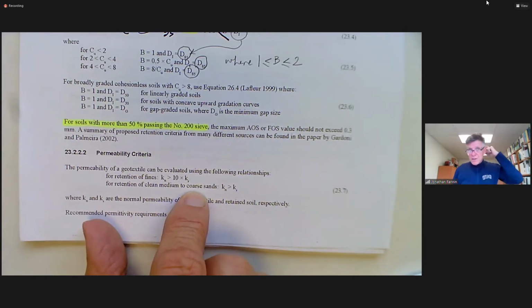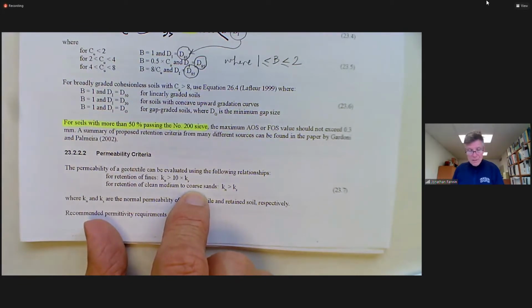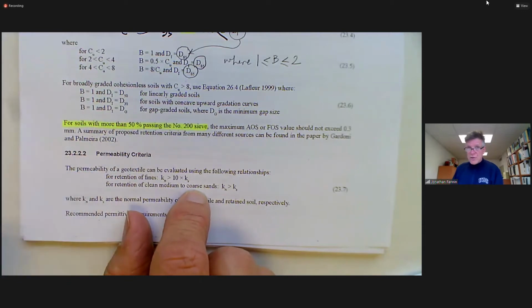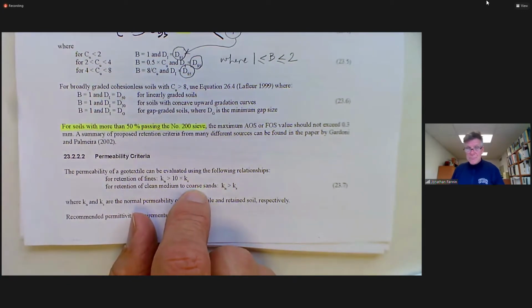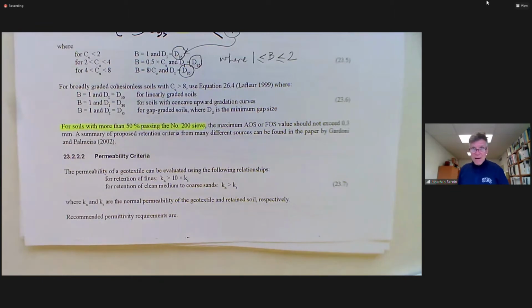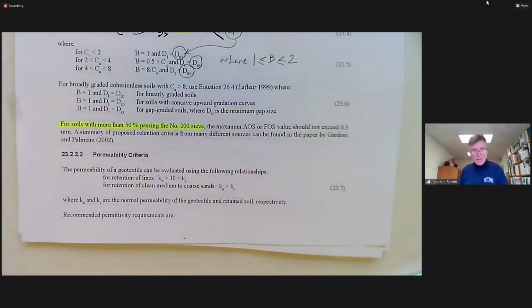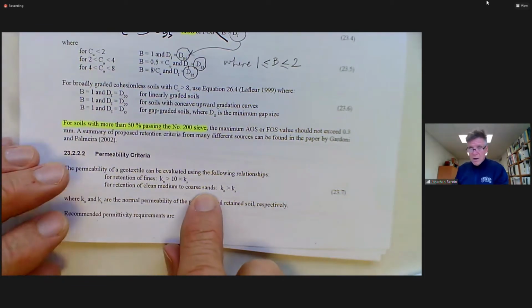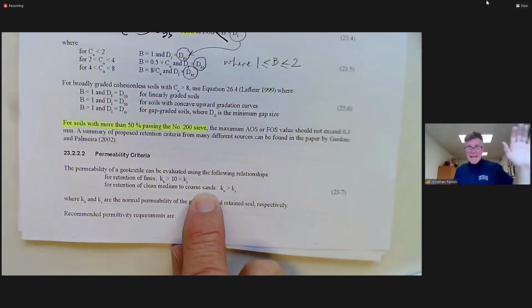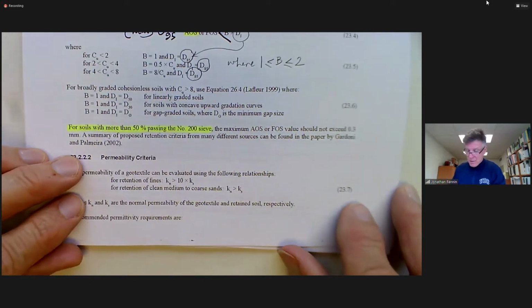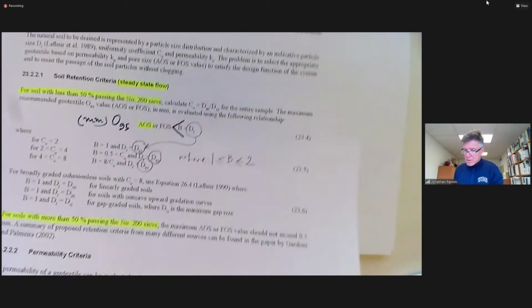And she took a look at it and said, no, I can't accept this, and instructed the contractor to actually punch holes in the geotextile. If you're going to cover that with riprap rock, I want you to punch holes in it, because otherwise the geotextile that you're putting over top of these exposures, these interbedded lenses of sands, and some concentrated buried channels on these forested hill slopes, odds on that geotextile is going to cap, impede the flow. And she'd seen enough washouts in her time to recommend changing it.